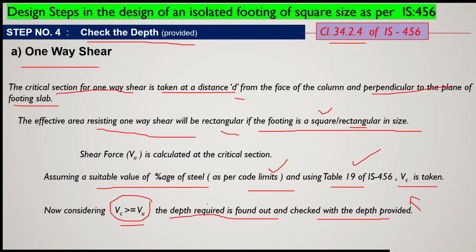So by applying the one-way shear check, we can find out how much is the depth required, and then we can compare it with the depth we have already provided.